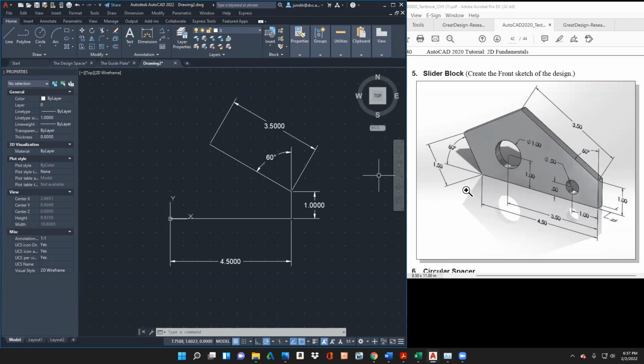So I'm going to make a line 1.5 inches, and I'm going to rotate it 60 degrees. So I'll take a line. That happened to be my 0, 0, so I can type in 0, 0, enter. I'm going to draw a line. Now you could, again, it shows you the 60 degrees. So the 120. So in theory, I could put it at 120 and then type in 1.5.